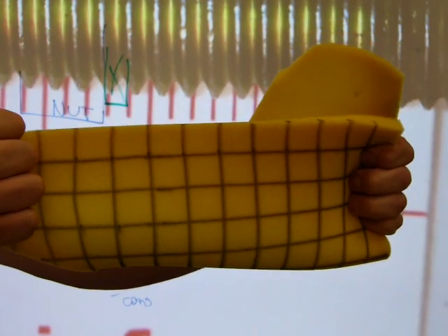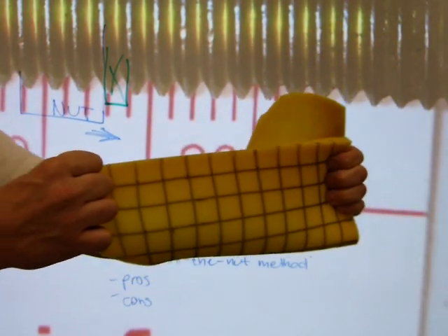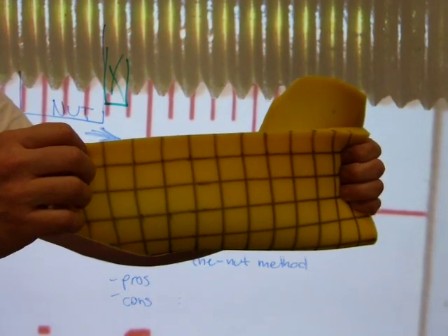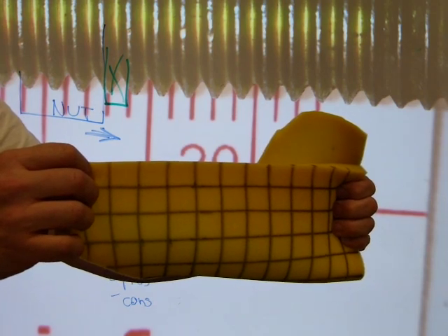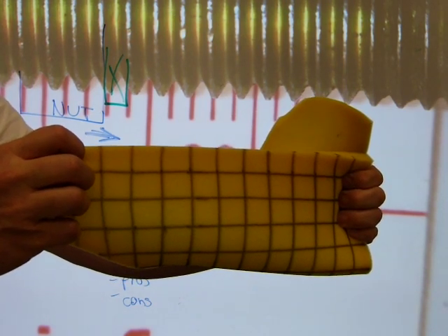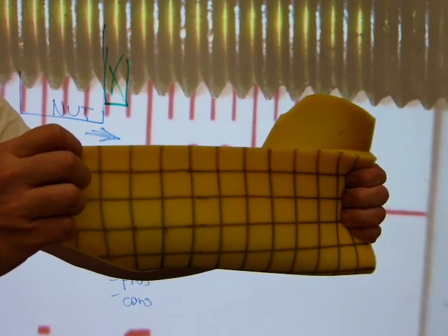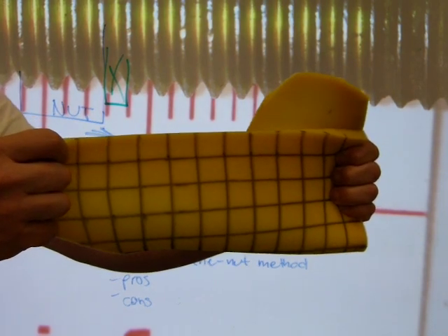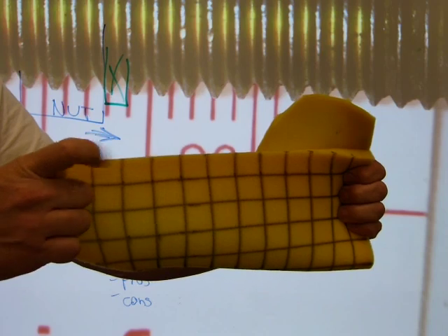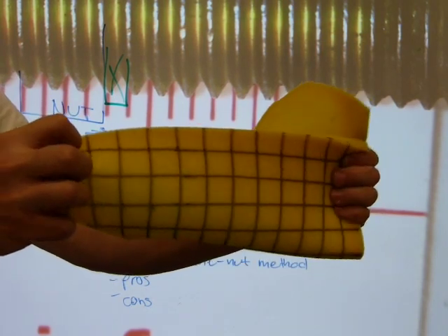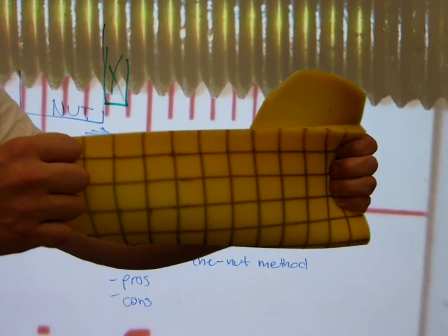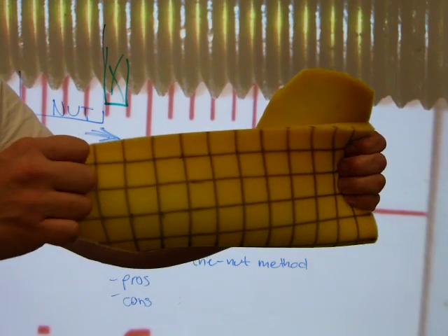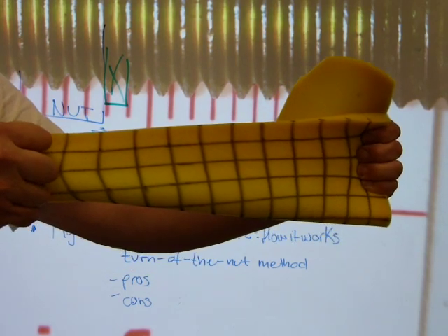It stretches. If this is the head of the bolt and this is a nut, and if the nut is forced to move along the thread but it can't because there is something in front of it, it's going to be clamping the material with a greater and greater force and will elongate the fastener proportionately to the amount of travel that it's forced to take forward. Okay? For example, if you take a quarter turn on this nut, it will stretch the bolt a little.